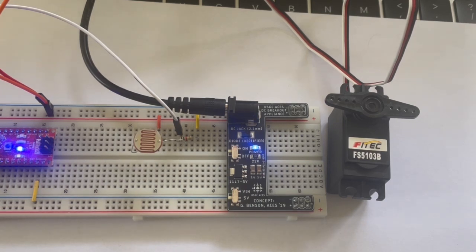The light dependency in the circuit comes from the LDR voltage divider that is read on analog pin 0 here. A well-lit room is about 70 in the serial monitor when constrained to a value between 0 and 180, so the servo is set to turn in an if statement when the LDR reading is about 30.